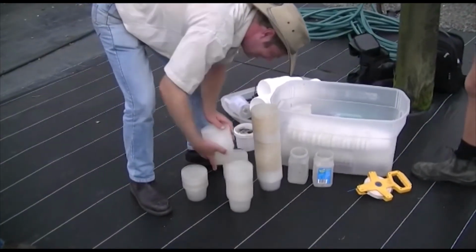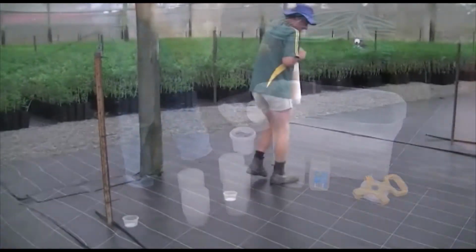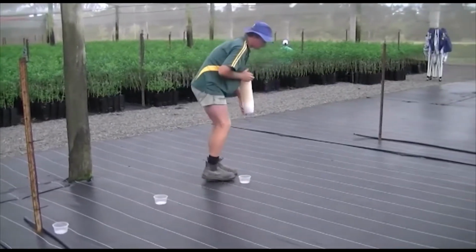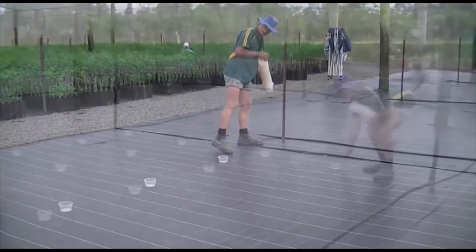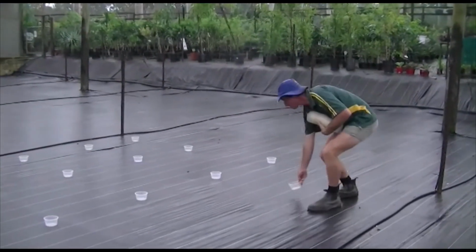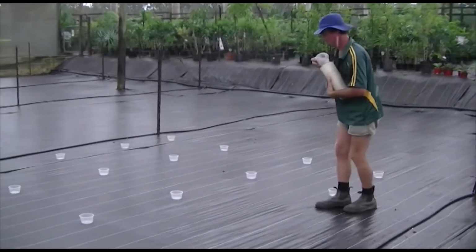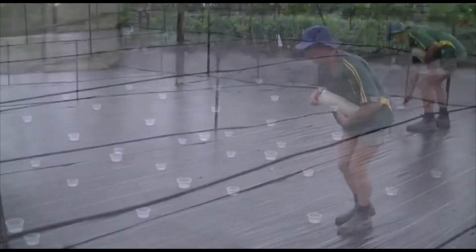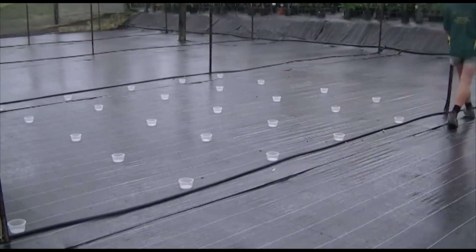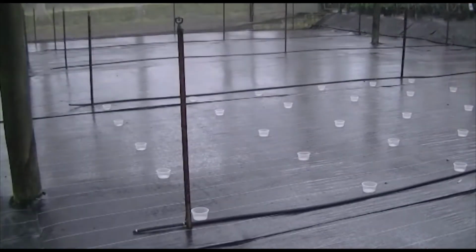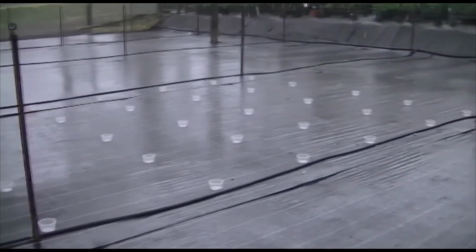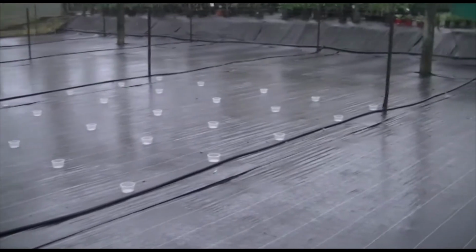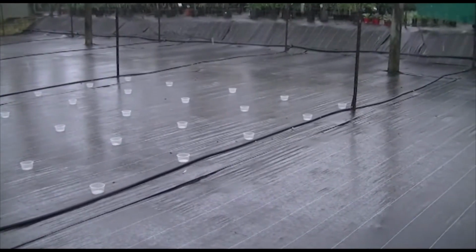After checking the system, the catch cans are set out in grid formation in the selected test area. Catch cans should be evenly spaced with a maximum spacing of 1 metre between cans. Ensure that all catch cans are the same size, in good condition, set out level, evenly spaced, and not restricted from collecting water from the irrigation event. Weights can be placed in the catch cans to prevent them blowing over if prevailing wind is too strong.